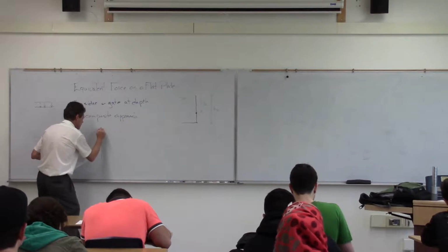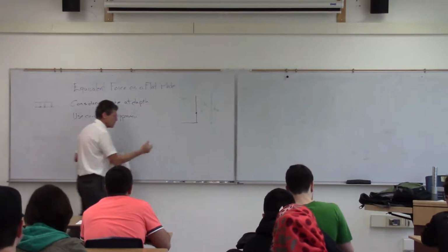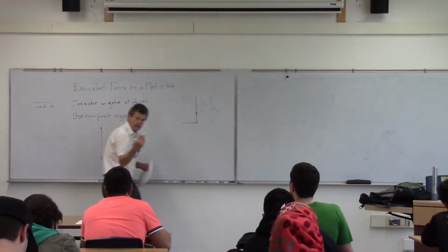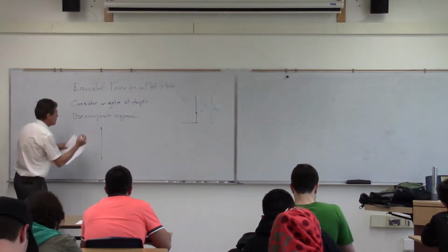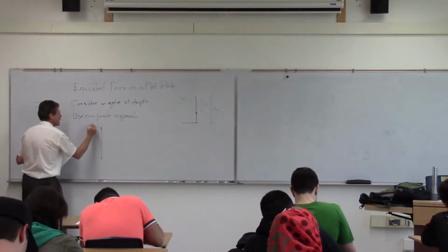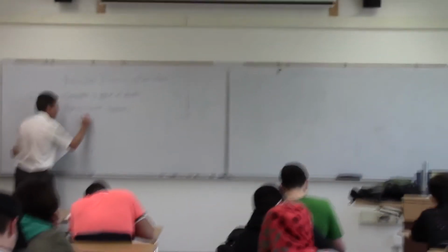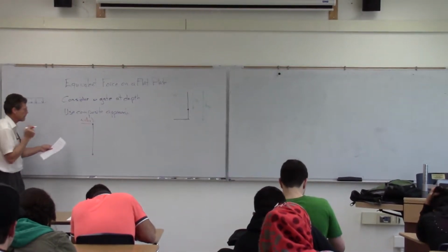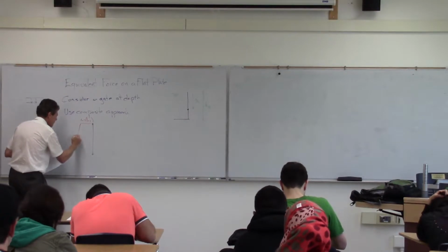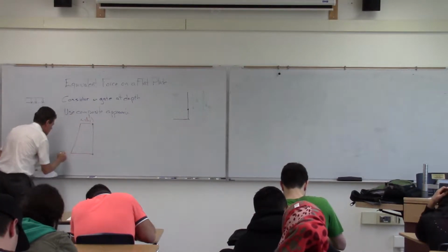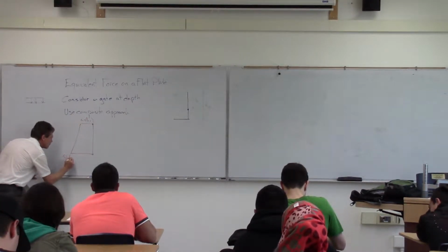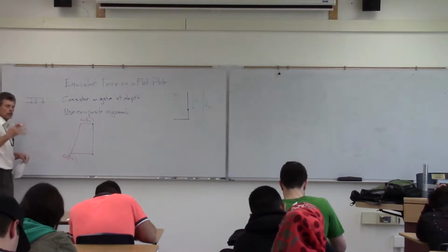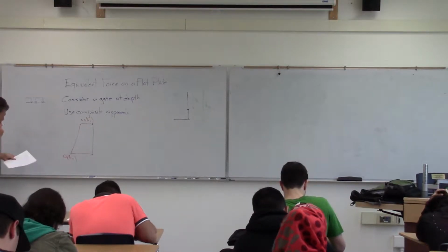So when we look at that gate by itself, what we're interested in is creating the load that's acting on that. And what we'll find is then there'll be a certain pressure here due to H1. And then when we get down here, it will linearly increase because H2 now will be bigger.